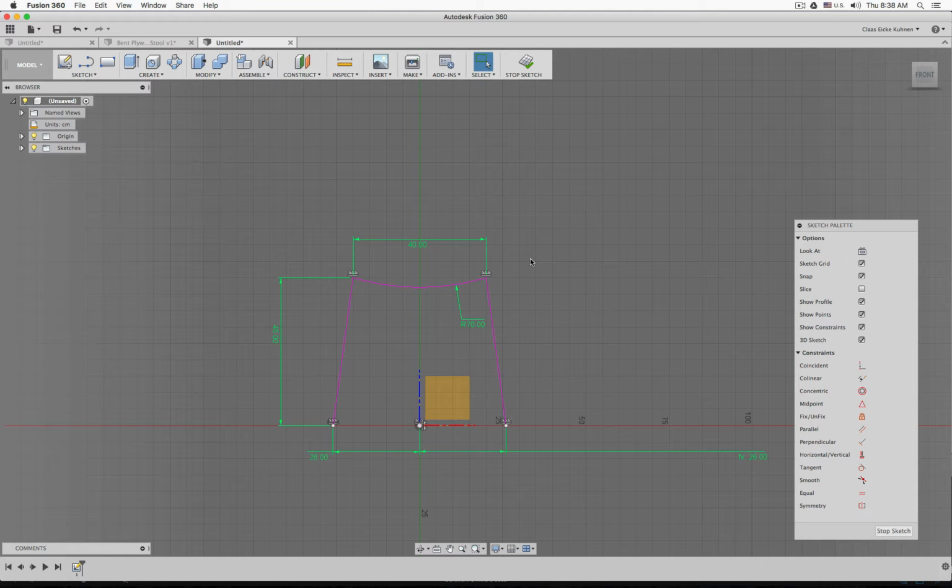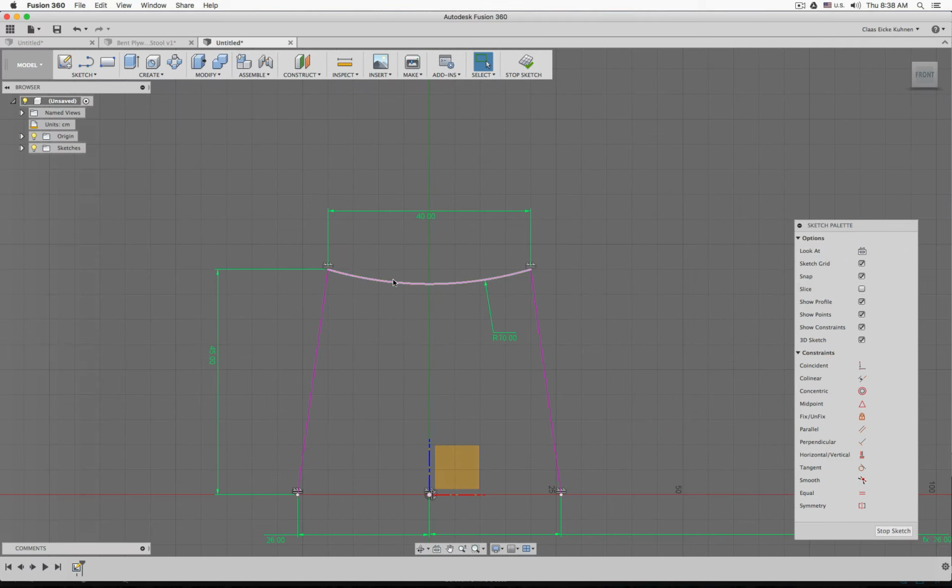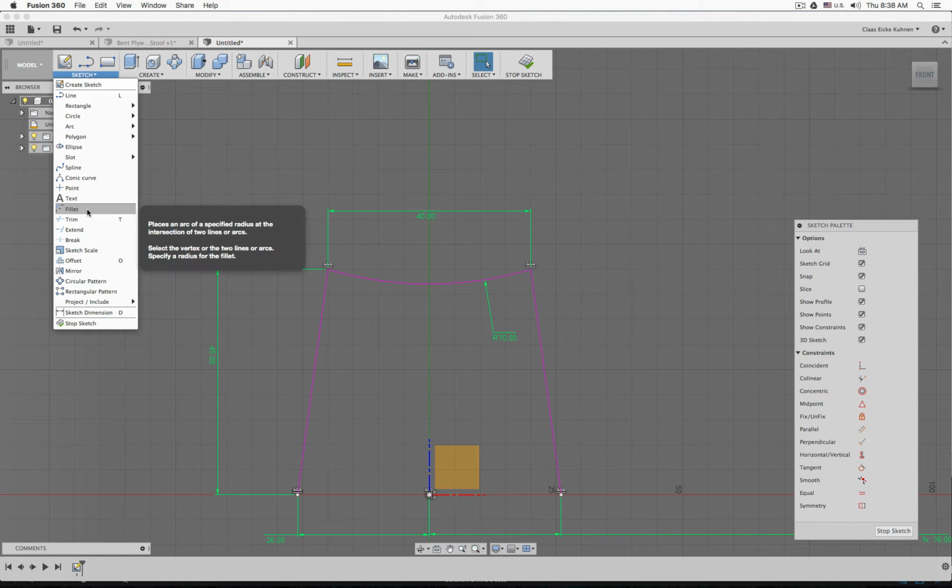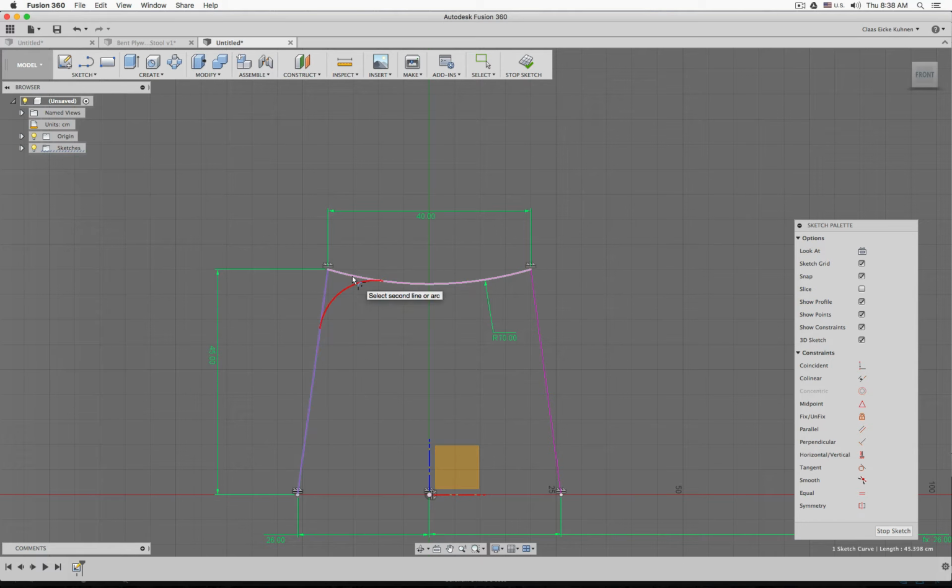So this is a little bit similar, geometry-wise, to what we did in Blender. And you see now here we created this arc, and then there we want to create the rounding as well. Well, we could go ahead and, for example, create a fillet. And there's our fillet. But the problem, as you can see, is a lot of my dimensions go away, and I also do not have this very basic line work anymore.